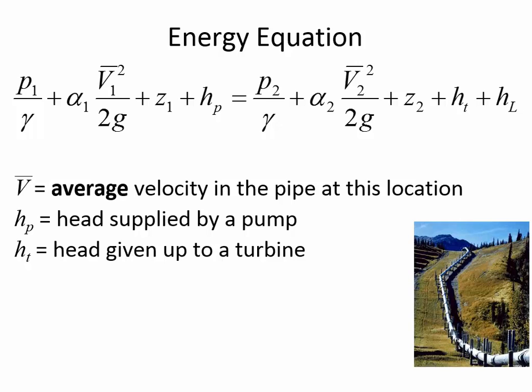That's a good question. Only in the most extreme circumstances of really high velocity. Otherwise, there's very little heat of the fluid. So water flowing through a pipe, generally the increase in temperature because of turbulence and pipe friction is not measurable. But there are circumstances where you can, if you have velocities usually in excess of what the pipe could withstand over the long term before being scoured. So like the type of velocity you'd need going through a pipe to heat up the water would cause a pretty rapid breakdown of the pipe before you saw a significant increase in the water temperature.